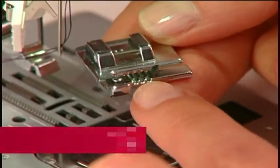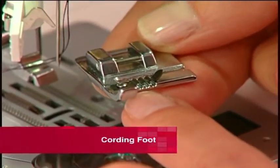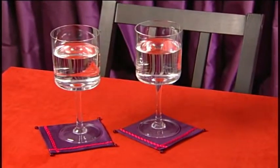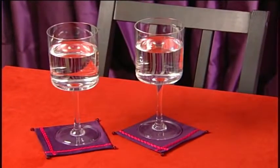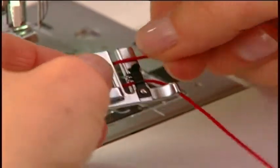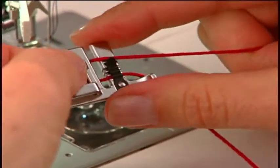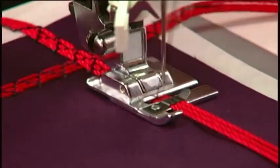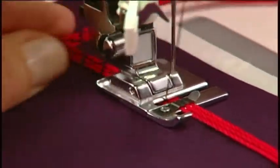The cording foot has grooves on the top, which are used to guide a yarn or cord. Stitches are sewn over cords placed into the foot, as the foot guides them evenly. To do fabric embellishment, place up to 3 cords into the grooves of the foot. Thread the machine, and then choose a decorative stitch wide enough to cover the cords being guided through the presser